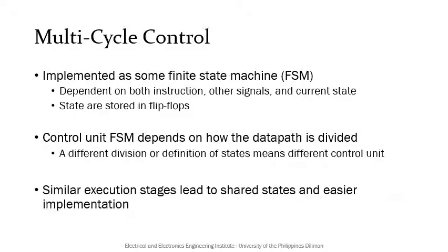Also, similar execution stages lead to similar or shared states and easier implementation. Aside from the first two states in our example, we were also able to merge the last state for R-type instructions and add-I. We also used a shared state for the third clock cycle for add-I, store word, and load word.